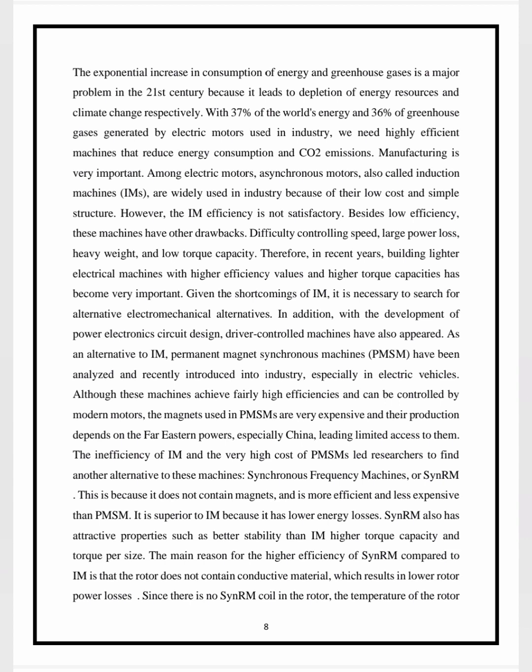Although these machines achieve fairly high efficiency and can be controlled by modern drives, the magnets used in PMSMs, permanent magnet synchronous machines, are very expensive and their production depends on the Far East, especially China, leading to limited access to them. The inefficiency of induction motors and the very high cost of permanent magnet synchronous machines lead researchers to find another alternative to these machines.